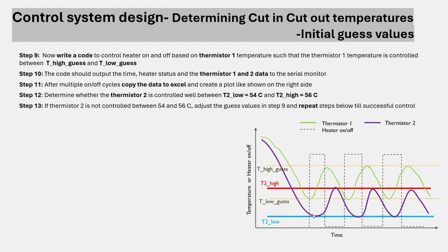And you don't have to control it exactly to 54 and 56. It could be inside 54 and 56. So for example, you can control it to 54.2 to 55.8, because that will be inside, right? So adjust such that it's always inside. That's all that is required, that the temperature of the center of the water does not go outside, okay?